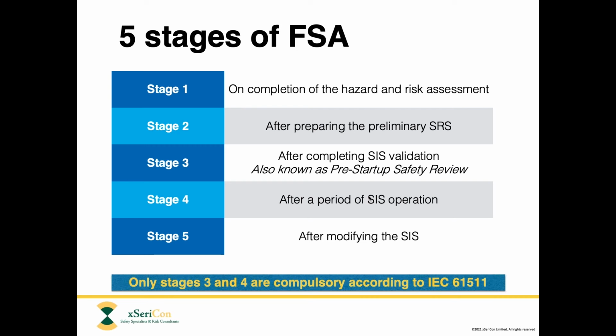So for example, when you perform the HAZOP study to identify the risks at the beginning of the functional safety life cycle, after completing the HAZOP, it should be verified to confirm that basically the outcome from it is correct in terms of it matches the inputs and it's suitable for use for the rest of the safety life cycle. And the same applies to all the other phases. For example, the SIL determination study, development of the safety requirement specification, development of the preliminary design of the SIS, and so on and so on. Each phase, one by one, needs to be verified.